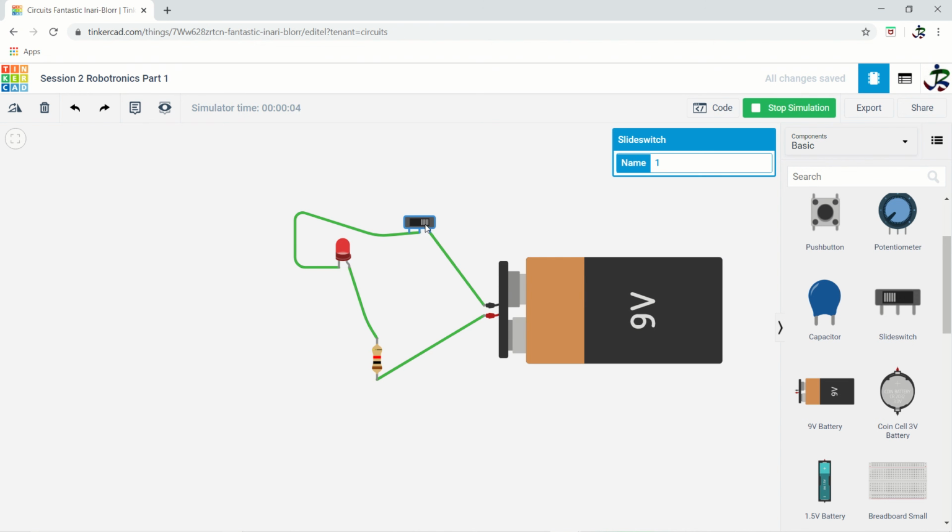Okay, so it depends on the power also, it depends on the resistor also. So here we have used 1 kilo ohm, so instead of 1 kilo ohm we will use 100. So 100 ohm is also having more current because of the 9 volt battery, and it is having 65 milliampere, which is very high because the recommended is 20 milliampere, so it works on 20 milliampere only.